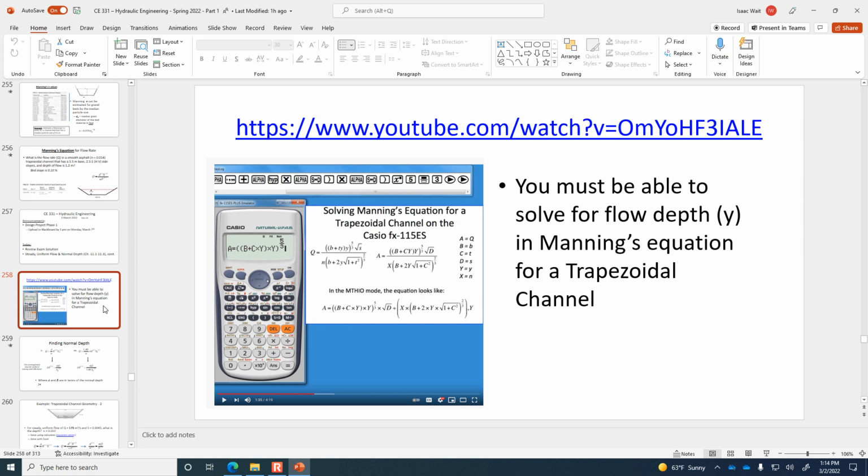The flow rate in a channel is the area to the 5/3 power, the slope to the 1/2 power, divided by the friction factor n times the wetted perimeter to the 2/3 power. All right, so that's Manning's equation.